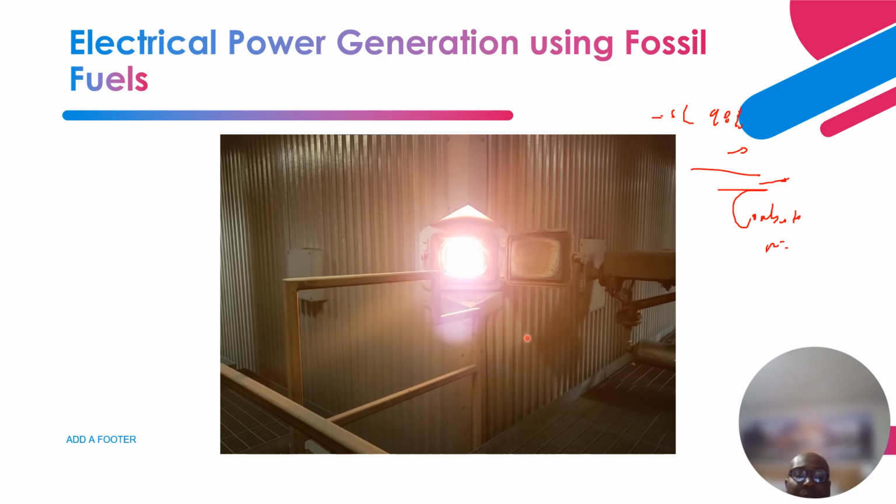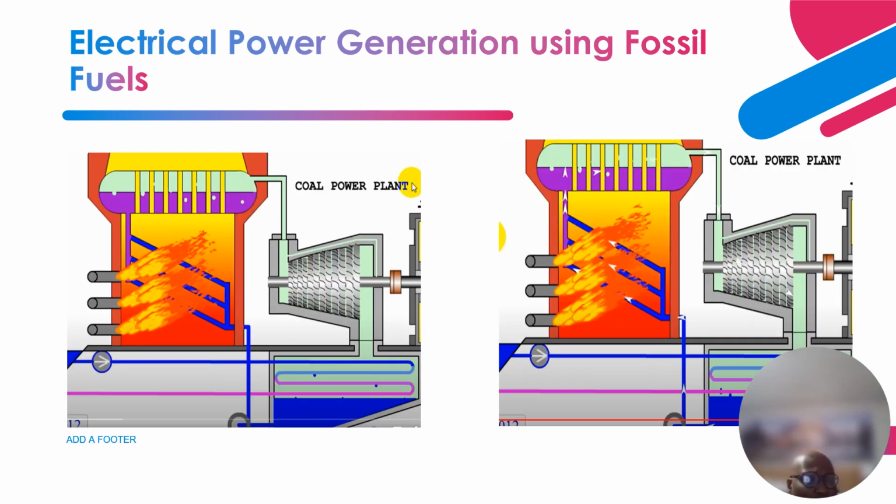As you can see over here, the pulverized coal comes in, and these are all the burners. The water gets heated, forms steam, rises up here, is collected and reheated, and the goal is to get it 98% dry before it gets into the turbine, right?